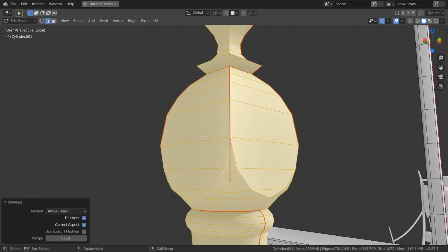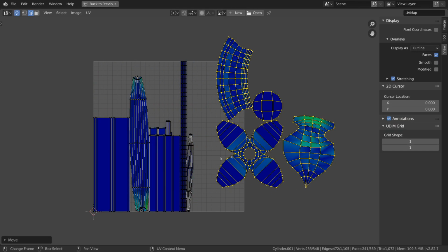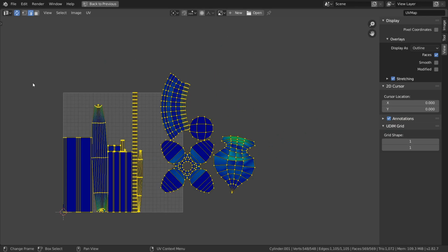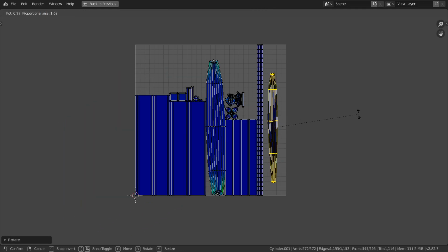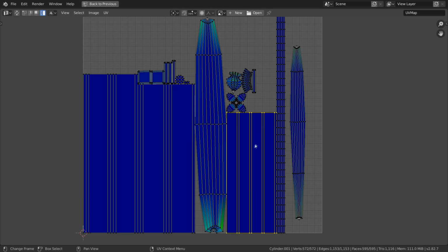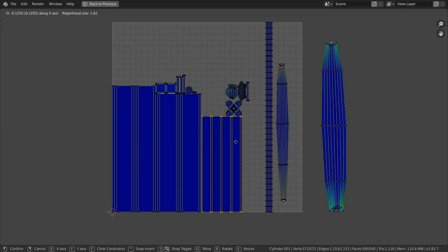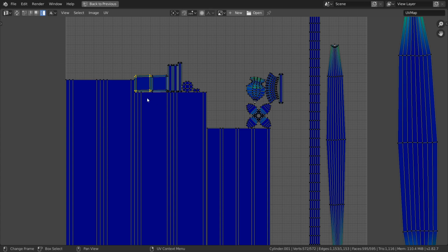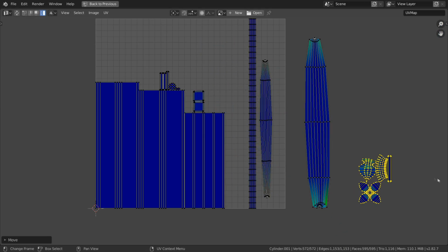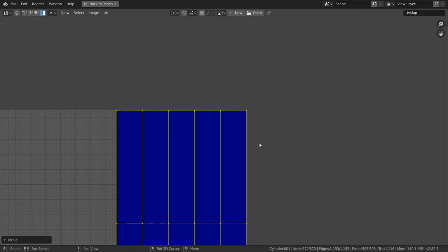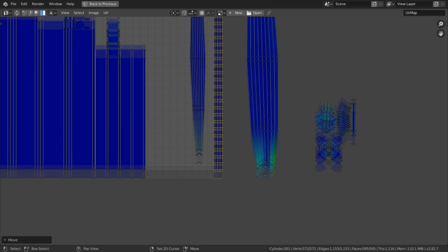You can also add a carpet if you want. In the UV editor you can visualize stretching of your polygons by pressing N and navigating to sidebar, view, overlays, stretching and changing the type to angle. It's a crucial feature, so I don't know why it's so hidden. Maybe in the future updates of Blender it will be just a single button on top of the bar, who knows. Since there is some stretching on a dolly, I add more edges and extend seams to unfold mesh better.